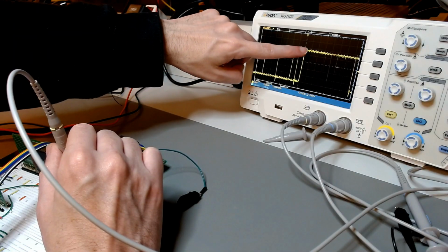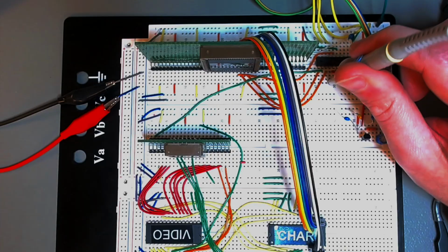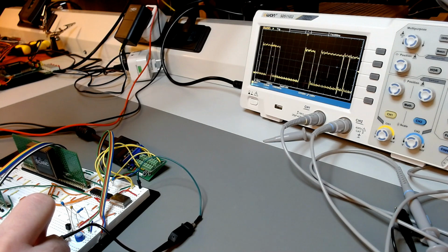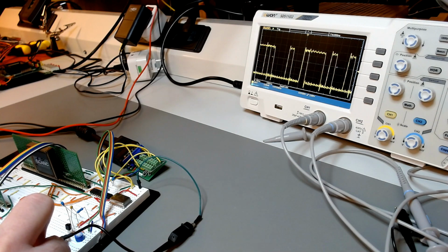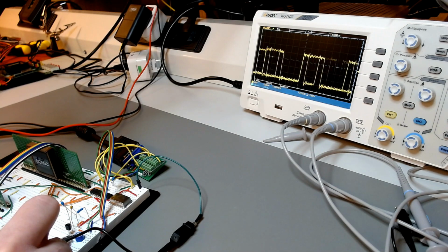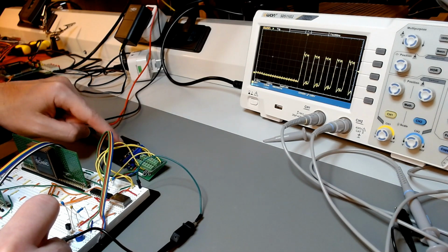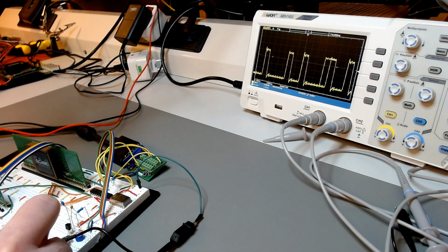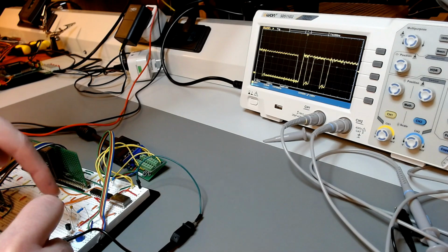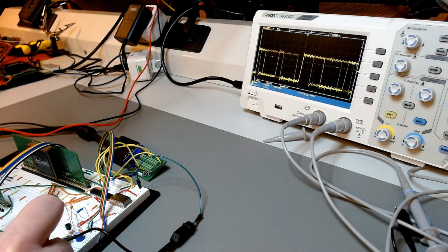So this is roughly at 4 volts, and it goes through the buffer and comes out on this side, and now we have closer to 5 volts, and then it goes through this buffer. It comes into the buffer here through the base, which is the same signal you just saw, around 4.5, 4.8 volts, and on the emitter is the output, and notice it's back to 4 volts. That gives you an idea what the load is here. It's a pretty severe load. It's difficult to drive this connector, the VGA cable and everything. So even with buffering twice, including with a high current amplifying transistor, the signal still goes down to 4 volts.